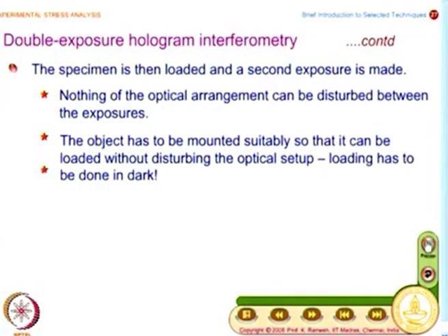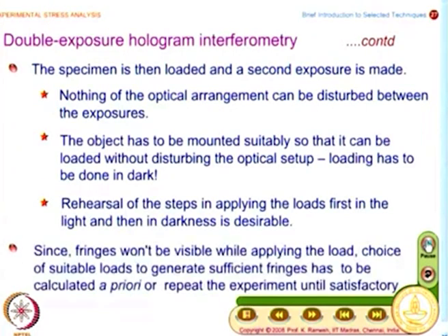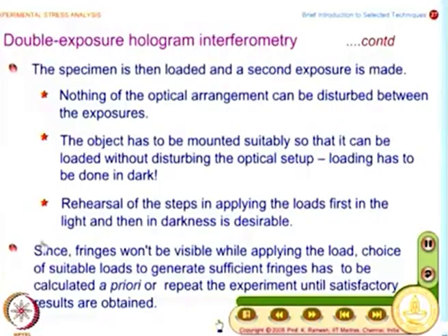The other difficult point here is, since you do not know a priori how the fringes are formed, you will have to have appropriate calculation to find out the extent of load that you should apply. What is advised is you do a rehearsal of the steps in applying the loads, first in the light and then in darkness. So, you have to do some practice.